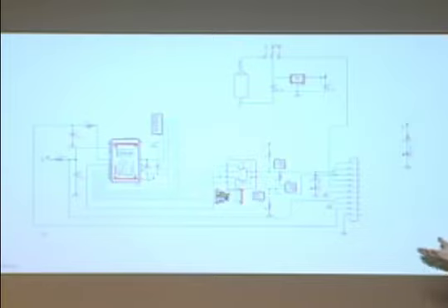We have a very similar circuit for the cap wire instruments, but instead of a pull-up resistor, we have a 555 timer, which incorporates the cap wire instrument as a capacitor in its circuit. The square wave output from the 555 timer varies in frequency depending on the capacitance of the cap wire, so the frequency will be proportional to the depth. The microcontroller reads that data and sends it to the PC.